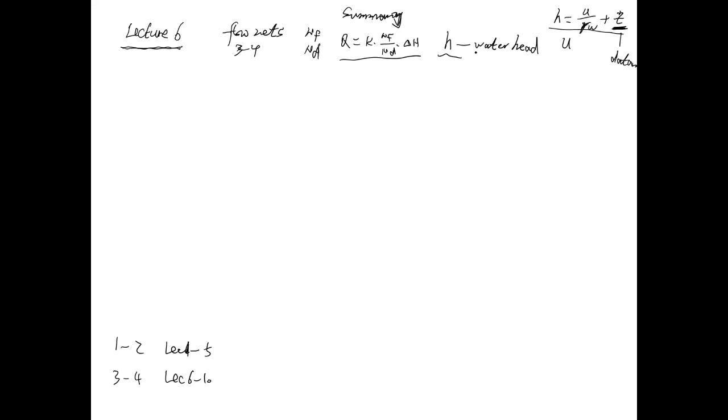So once you work out the total height, you are able to get the value of pore water pressure at any position. Pore water pressure could be upward or downward. If upward, that's uplift pressure. We already had lots of practice in tutorial 6, so you can go back to review the tutorial questions, the lecture, or even the lecture examples. So that's for the isotropic case.